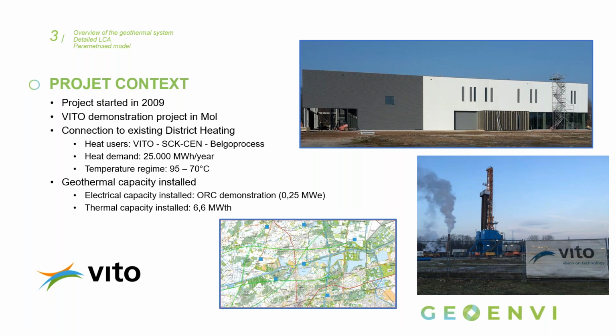The geothermal wells supply heat to an existing district heating network, heating the campus of VITO and neighboring companies, here SCK-CEN and Belgoprocess. The heat demand is about 25,000 megawatt-hours per year, and the temperature regime is between 95 and 70 degrees Celsius.